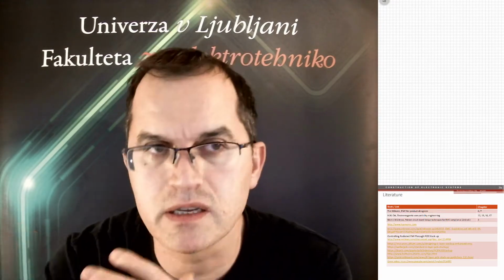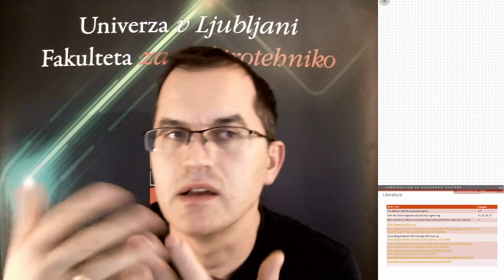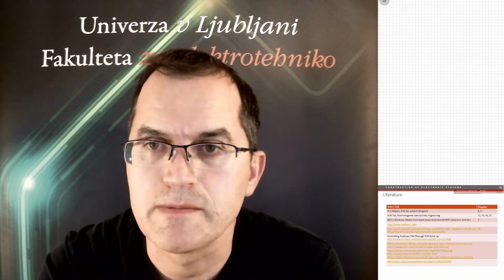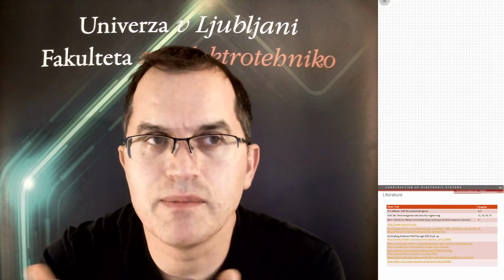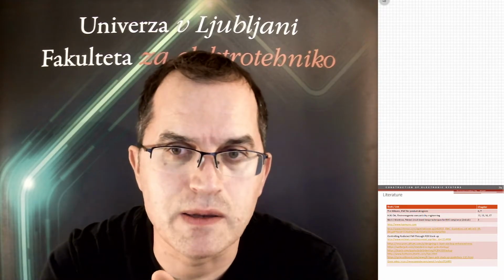And then you have to choose what are the layer properties, which of the layers will be used for ground, which will be used for power, signals, and so on. Whether you would use double layer placement of components or just on one side, whether we use through-hole wires or maybe micro wires. But then you can make the PCB and it actually works, so you're happy, but doesn't mean that it will actually go for the EMC.